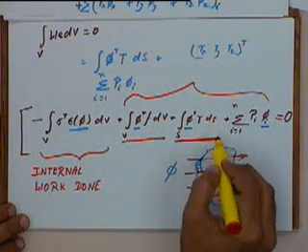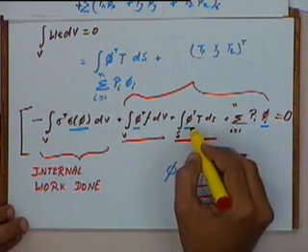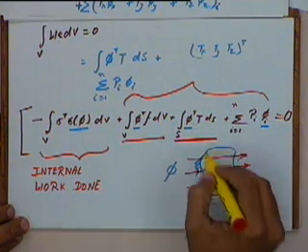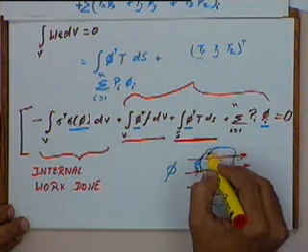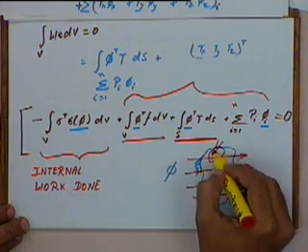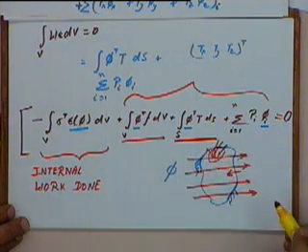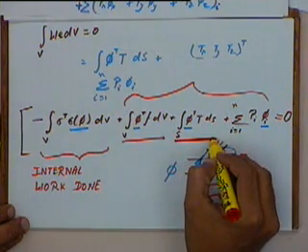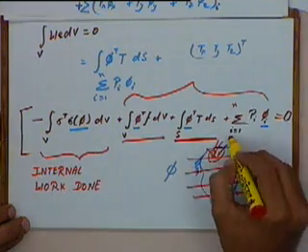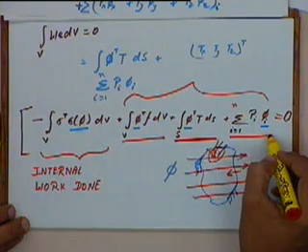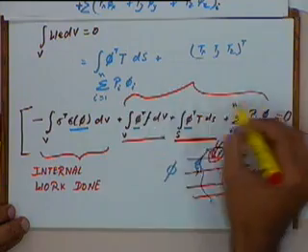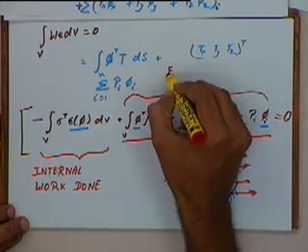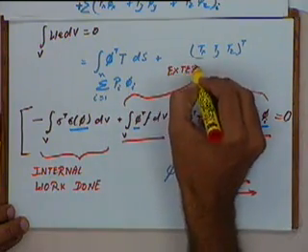Okay. Now if you look at this term, this is the work done by the virtual displacement against the tractive forces. That means if there are any forces acting on the surface, that is a pressure or force acting on a per unit area basis, then this term will give us the work done against that, and this will be the work done against the point loads. Okay. So these three terms will give us the external work done.